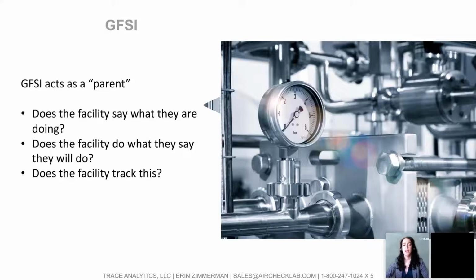So ultimately, GFSI wants to make sure that we're all saying what we do and that we're doing what we say and that we're documenting it. And that goes especially for compressed air monitoring too. So it's not just enough to check a box and say, hey, look, I tested for my audit. We actually want to take a look at the risks associated with contamination and make sure that the compressed air or gas quality is appropriate for your individual usages.